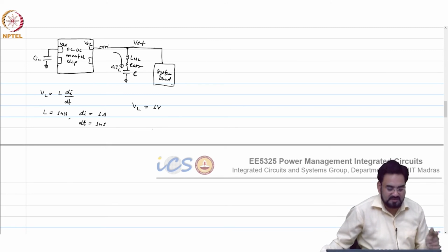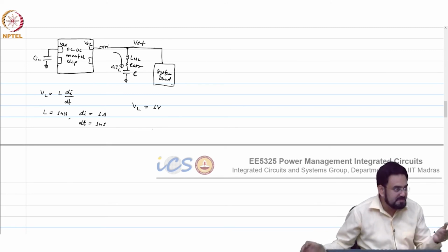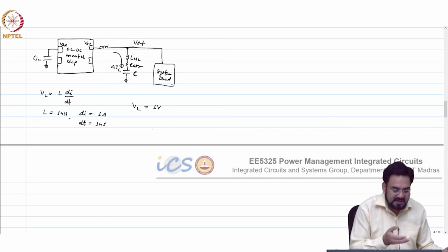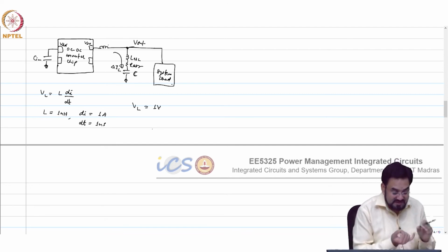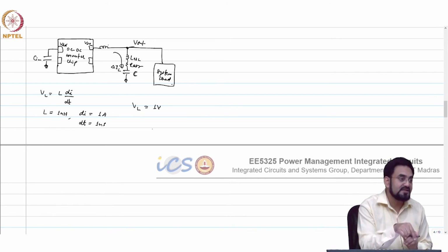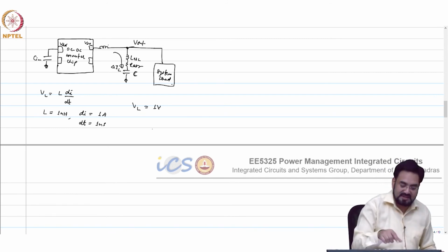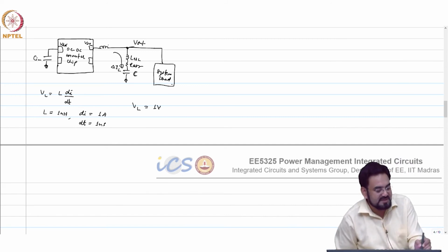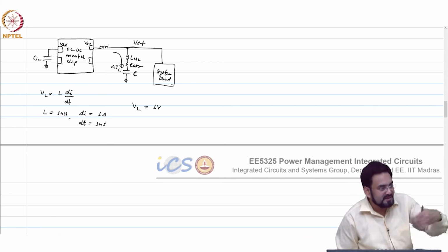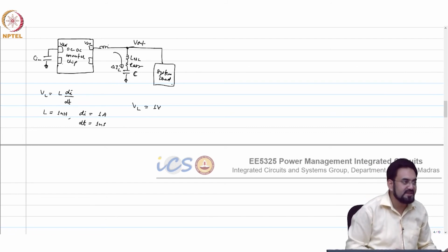If that ESL is large, let's say I can afford maybe plus minus 100 millivolt or so, then the value of L you require here is the equivalent series inductance, or parasitic inductance, associated with that C-in, which will not include the inductance of C-in itself. When I say LESL is inherent to C, but whenever you connect this capacitor to your VDD node or any other pin, that trace will also add, because that will be in series with LESL. So the total inductance we are looking at is maybe 100 picohenry or so in this case.